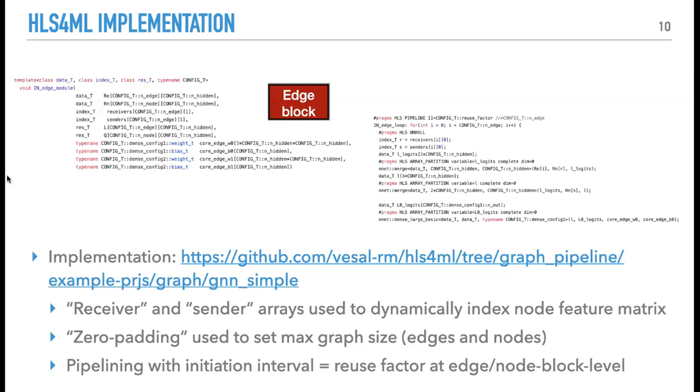So that's actually one very difficult part of the FPGA implementation. Right now this is probably one of the most resource consuming parts because you need to dynamically index things. And in general with FPGAs, you want to know as much as you can before you compile it. In this case, we're compiling something where it knows it needs to dynamically index something, and that's a very difficult step for it. So we have ideas related to pre-processing the graph in a certain way, which might help reduce the resources quite a bit.